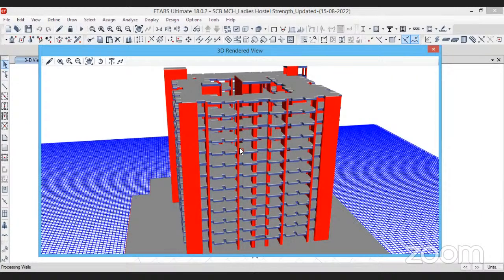But it needs certain plugins from structural, from architectural to ETABS, from architectural to STAAD. What happens is the visual features, the graphic features will not be available. It is possible only from other software to this software. Means from ETABS to Revit, from STAAD to Revit, from AutoCAD to Revit, from SketchUp to Revit, it's possible. But from Revit to ETABS is not possible because once you do that, the modeling activity will change. From this to that is possible, from that to this is not possible.